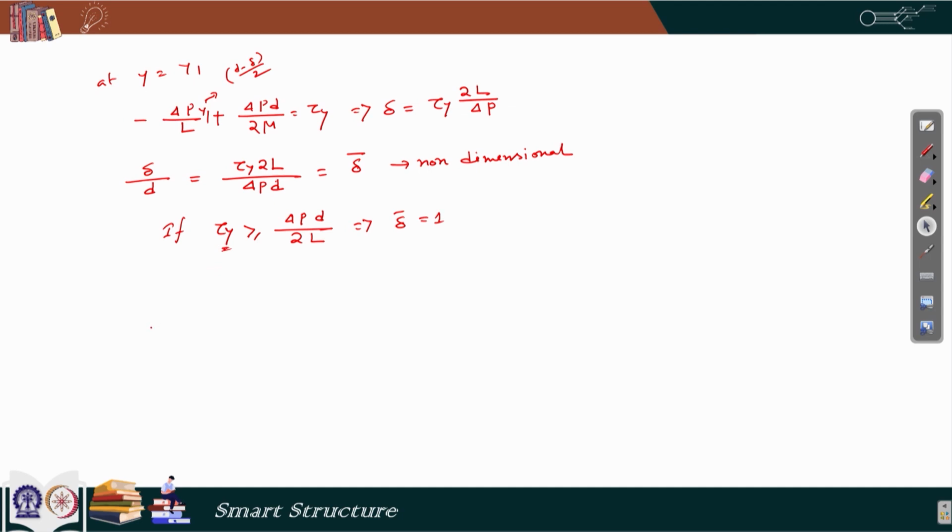Now, we have to find out the equivalent damping, and for that we would proceed with the same approach. We will assume that there is an equivalent velocity u m, and we will find out the flow corresponding to that in terms of u m, and then we will find out the actual flow, and then we equate both the terms, and that would give me u m.